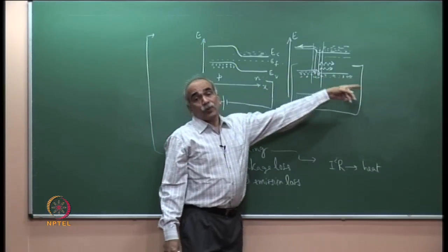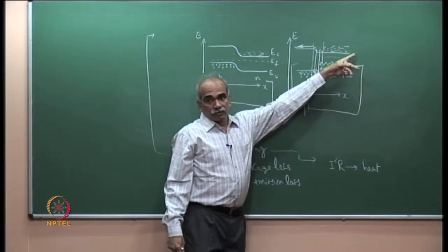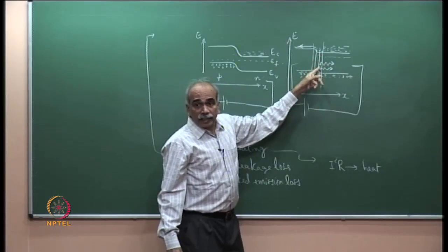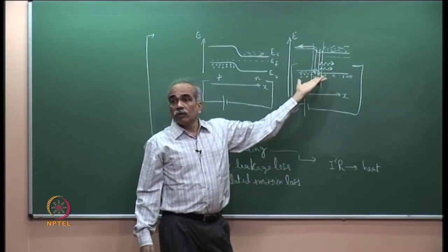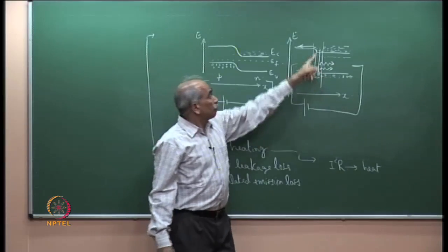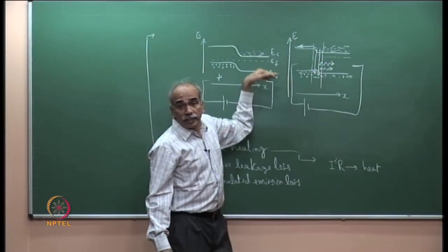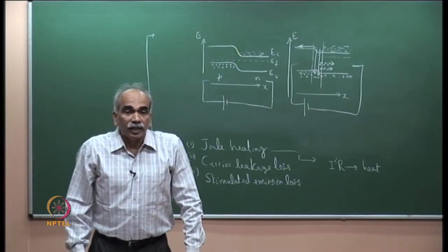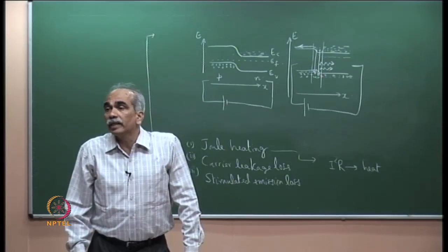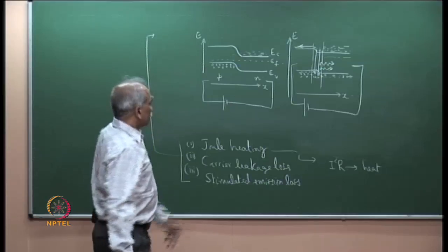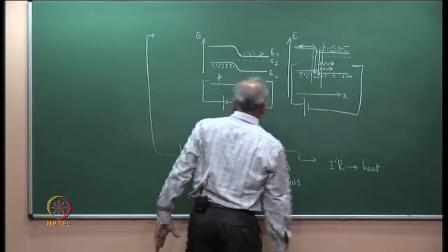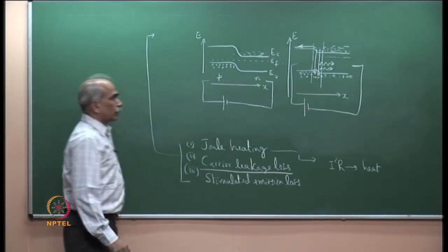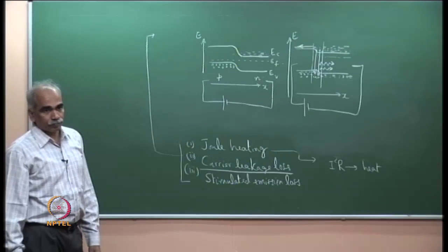So although you are passing a higher current, recombinations are taking place, generation of light is taking place, but some amount of carriers leak without leading to recombinations and therefore without contributing to generation of photons, and that leads to the saturation. Second effect, carrier leakage loss, which leads to saturation, is this.